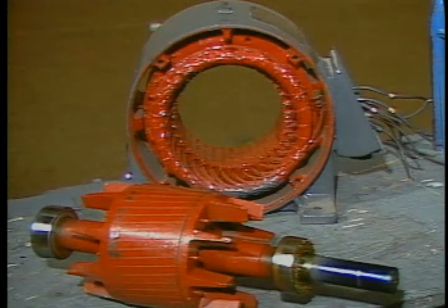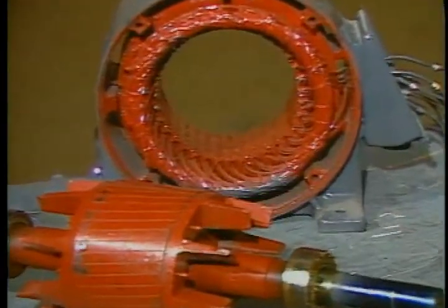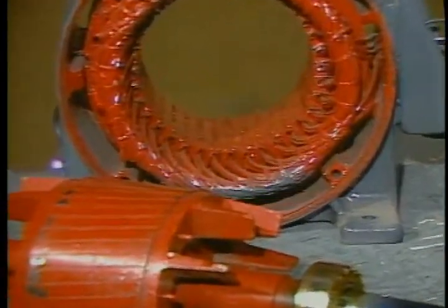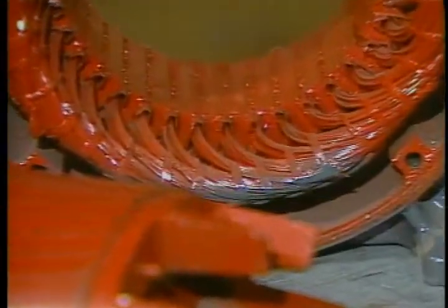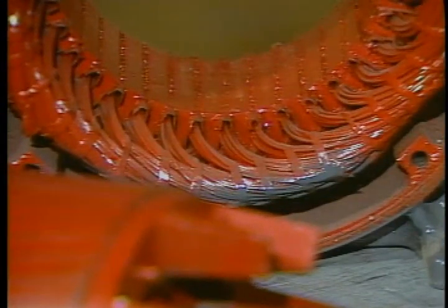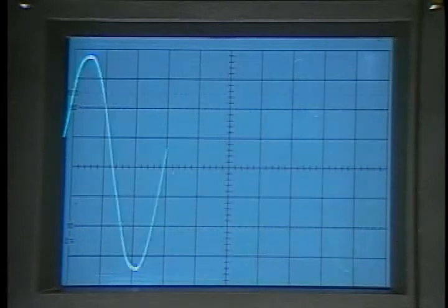Unlike a DC motor, AC motors usually have no brushes or commutator. Also, the stator windings are not on separate pole shoes, but in slots in a continuous core. In an AC motor, no switching is necessary because the current itself alternates. In other words, it automatically reverses direction.